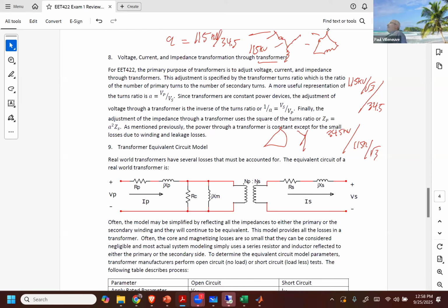So maybe parsing through the data sheet and finding the right data might have been a little bit challenging, but I think what most people probably missed was, when do I divide by the square root of 3 and when do I multiply by the square root of 3? That's why that homework was a lot harder than you probably thought, because I even showed you the data to use, on pages 9 and 10. But I didn't tell you about using the square root of 3. I wanted to see if you would be able to pull the two together. Whenever you're dealing with three phase, you've got to convert it to single phase.